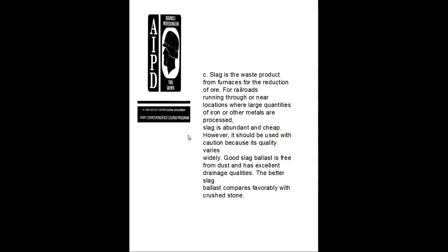Slag is a waste product of the furnace reduction of ore. For railroads running through locations where large quantities of iron and other metals are processed, slag is abundant and cheap. However, it should be used with caution because quality varies widely.